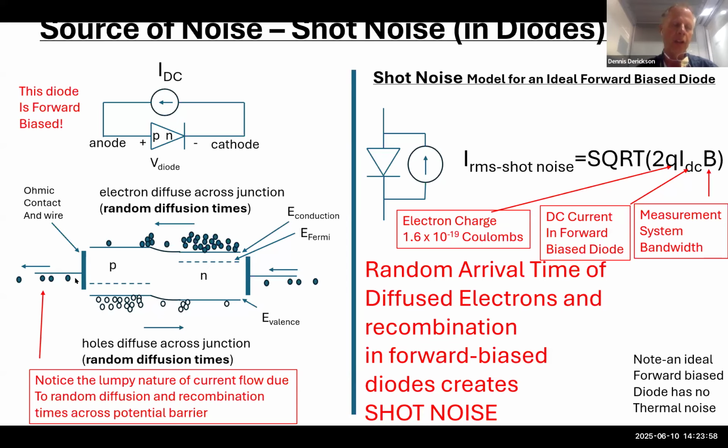But the external circuit will take away electrons here, creating more holes to keep this population of holes replenished in a steady state manner. So I first talked about electrons diffusing from the N-type material to the P-type material, then getting eaten up by the holes, and that causes a diffusion current.